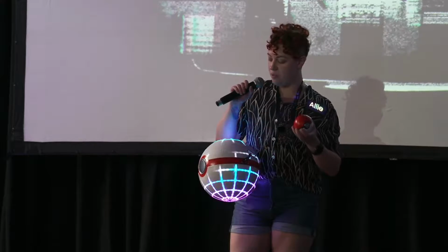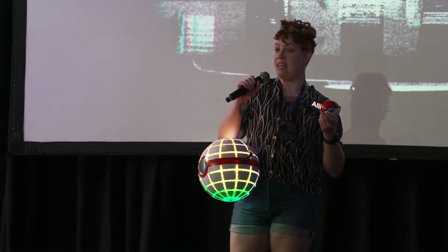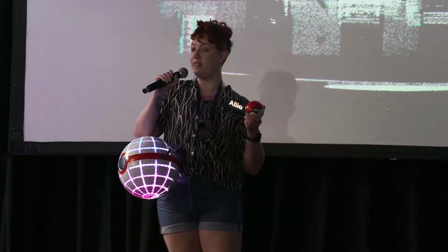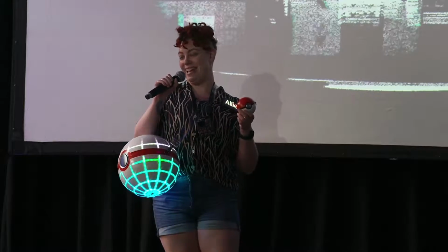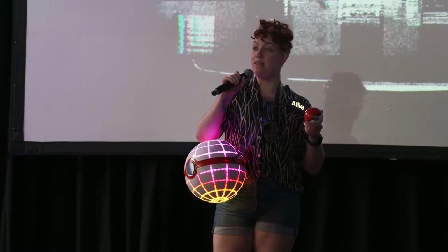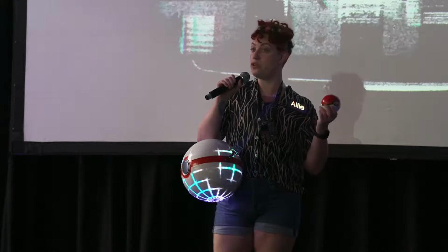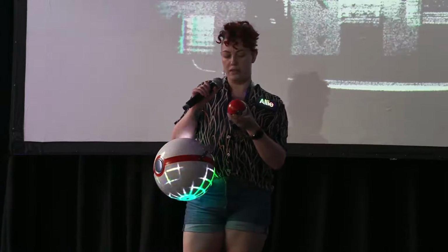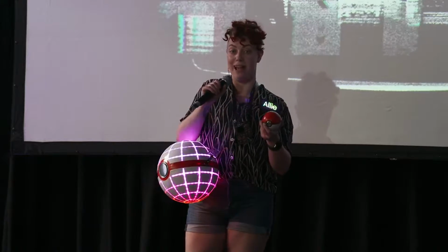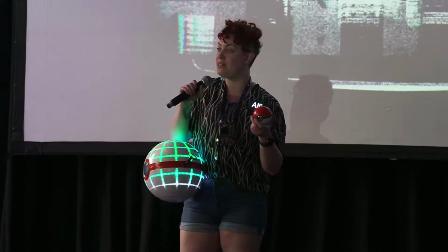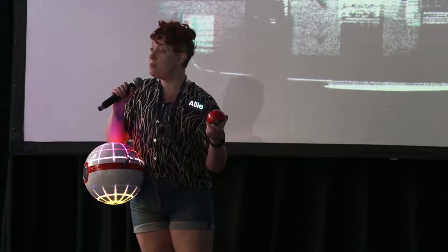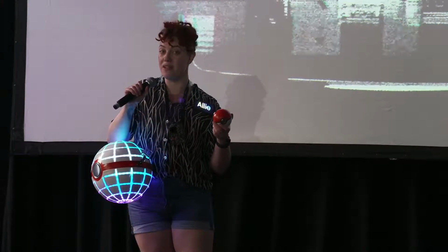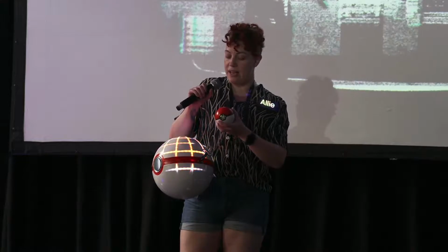So it is actually what is known as PVB. And please don't ask me exactly what that stands for. Somebody in the audience probably knows. I don't know it off the top of my head. But it is incredibly similar actually to PVA, which you will know as either soluble supports or Elmer's glue. And so PVB is a wonderful filament to do this sort of thing with, because it prints like PLA. 210, 215 Celsius on your printer, no enclosure, no special settings even. You can literally print this under a PLA setting. And then it is smoothable with isopropyl alcohol.